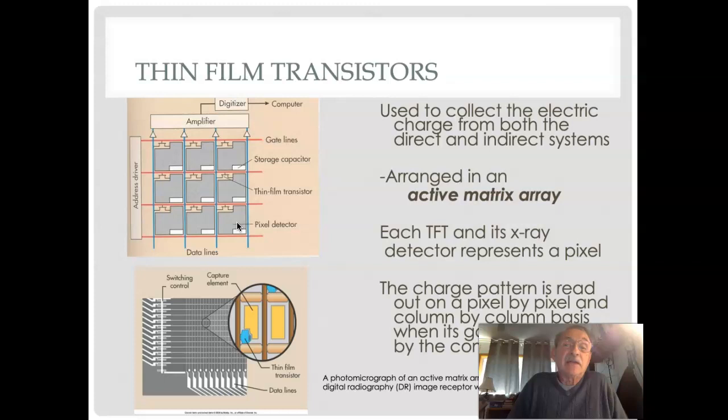And so as the voltage is applied to that first line through the gate line, then that row, all of those values are sent, and then that gate line is discharged, and then we charge the next one for the next row. And so this is how we can keep track of which pixel represents how much value.